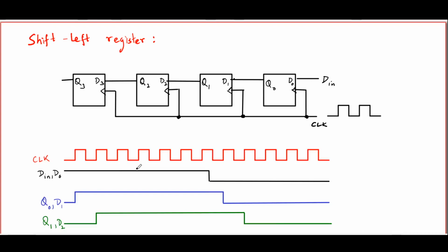The next register that we talk about is a shift register. Now a shift register does not merely store an input set of bits, it actually shifts the bits to the left or to the right depending on what kind of register it is. And this kind of shifting operation is essential for many arithmetic and logic manipulations that are carried out in digital computers.